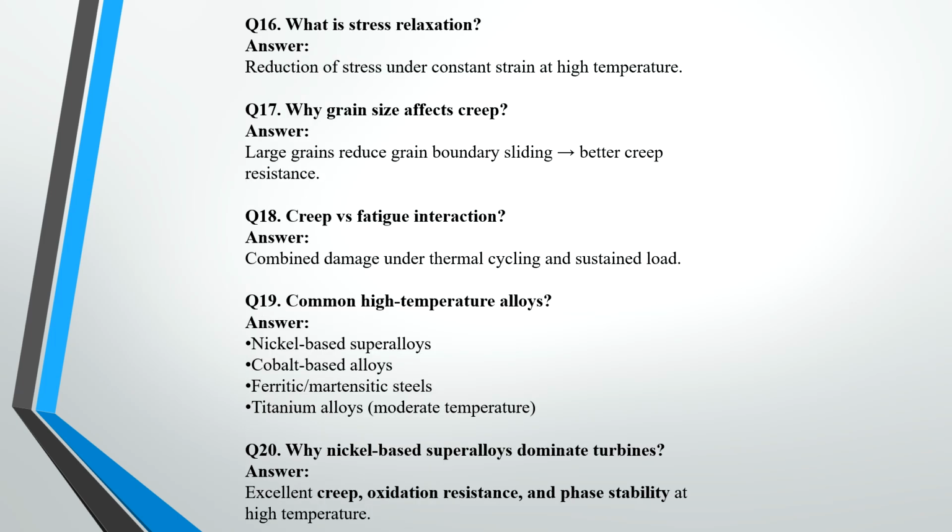What is stress relaxation? It's a reduction of stress under constant strain at high temperature. Why does grain size affect creep? Because large grains reduce grain boundary sliding, which leads to better creep resistance. What is creep versus fatigue interaction? It's combined damage under thermal cycling and sustained load. That is called creep-fatigue interaction.